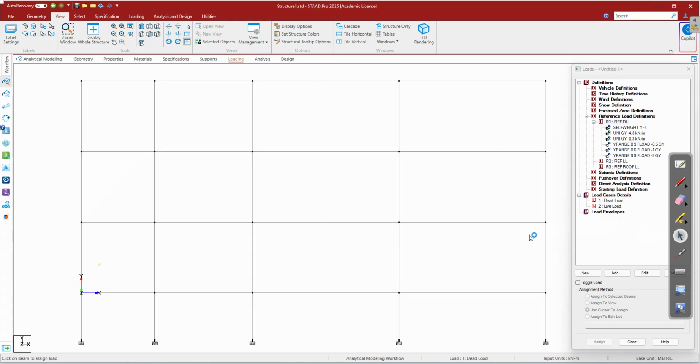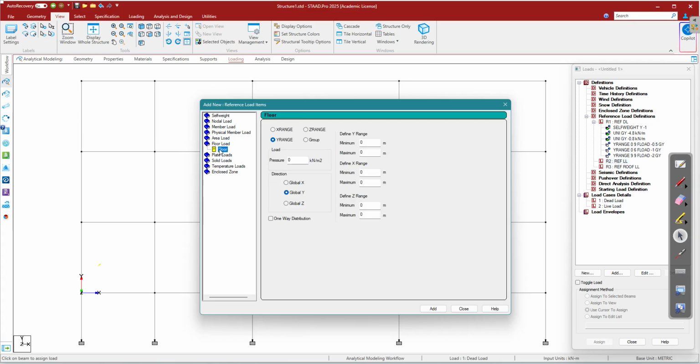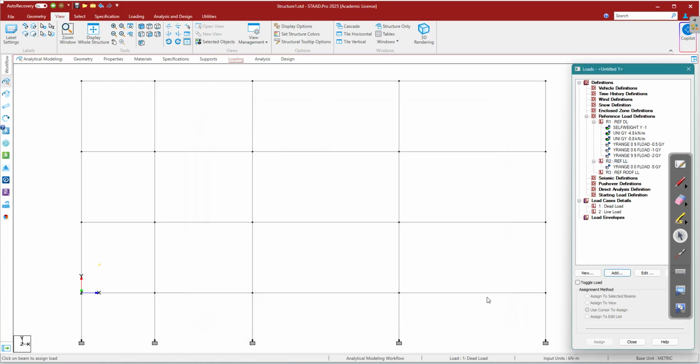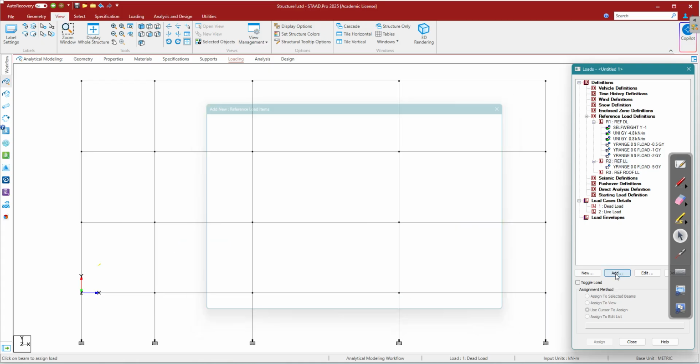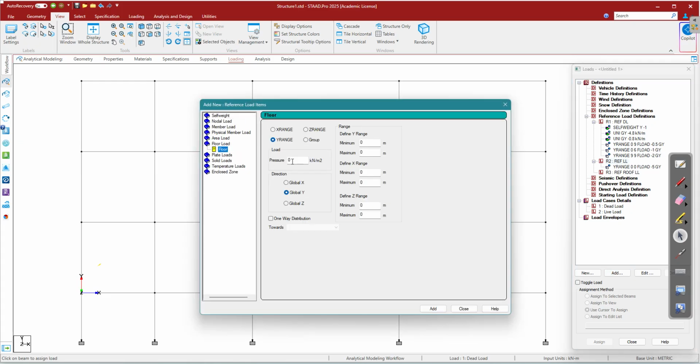Okay, I will be working in this front view. So you go to live load, you click add floor load, it is -5. So range is 0 0 0 0. You click add, close. See here, it is used as storage. So live load is in this region only.